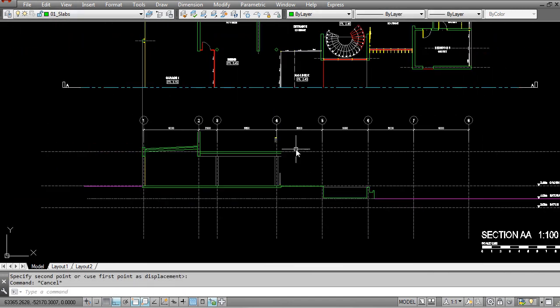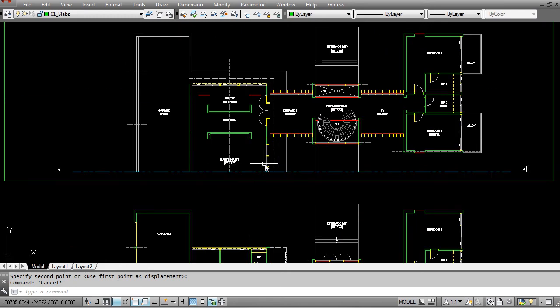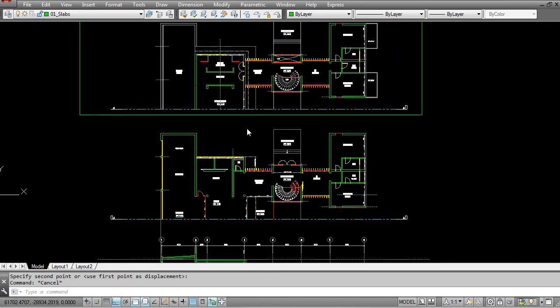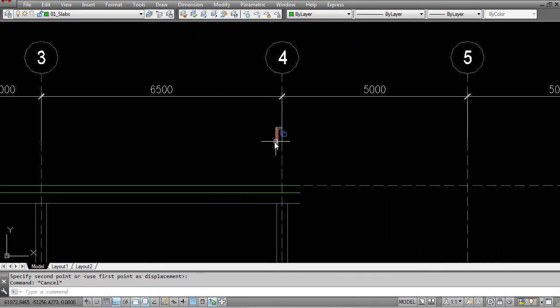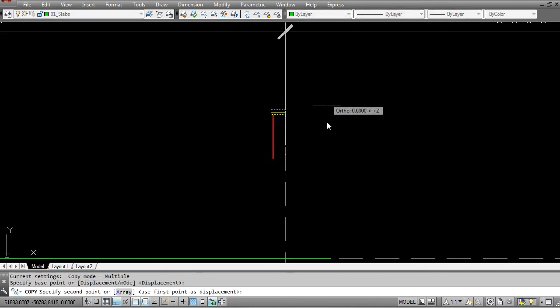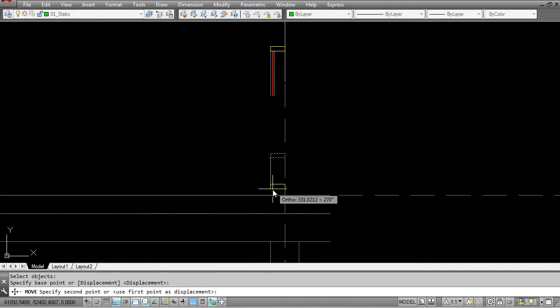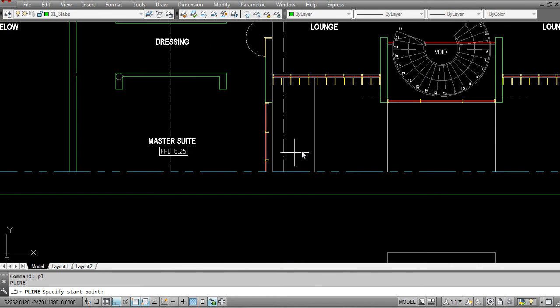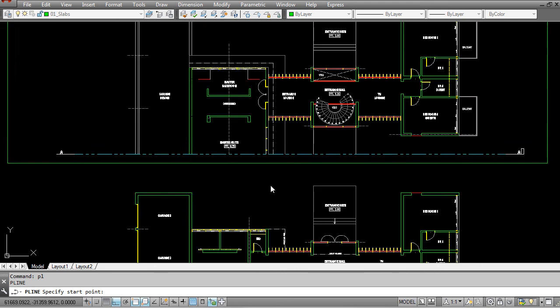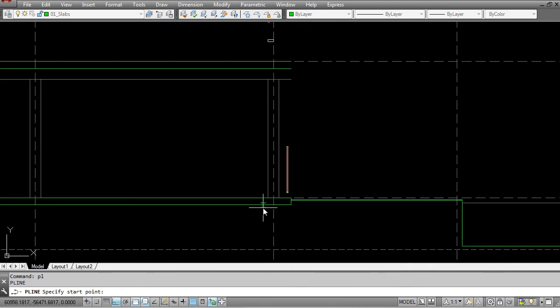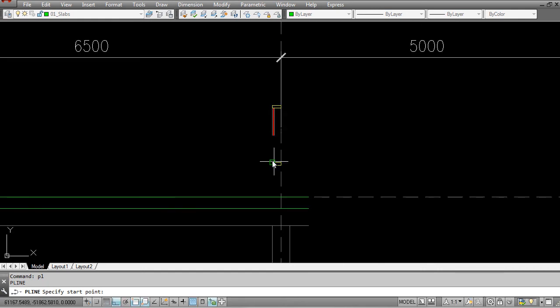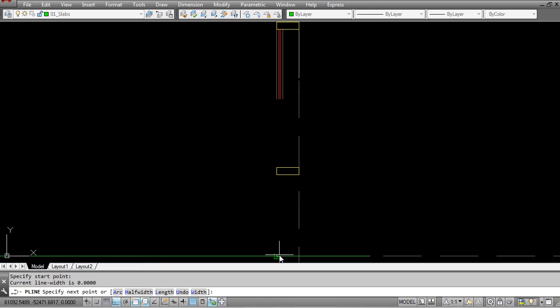So what I'm going to do is, next I'm going to have a look at any other major elements that I need to focus on. So we already have this glazing facade in place. We're going to have this frame coming down at the bottom. There's going to be a planter there, so I need to factor in that there will be a planter happening here. So it could be that this wall is actually going to be a little bit of an upstand, so that we can get at least a 400-500 millimeter planting bed in place. So I can factor that in. Let's say 500 millimeters.